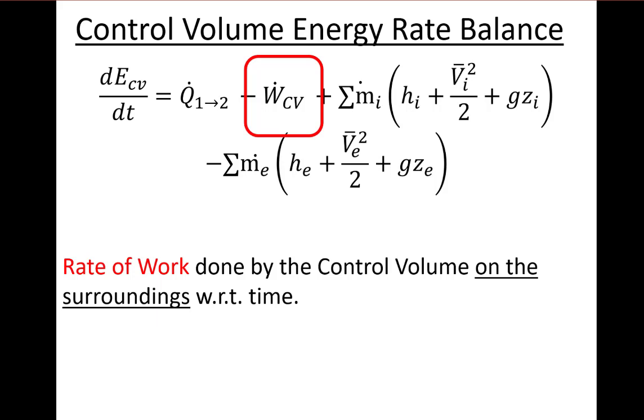So when you have a turbine, you have steam, or we'll learn later, air expanding through the turbine, and it runs over these fan blades, and that's what puts that torque on the shaft, which makes it spin. That's how you generate the power. And in a pump or a compressor, it's the opposite, where you plug that pump or compressor into the wall, you flip the switch, and that makes those fan blades spin, and that adds energy into the system. So basically, if this term survives, you're looking for fan blades or paddle wheels or something inside the system.